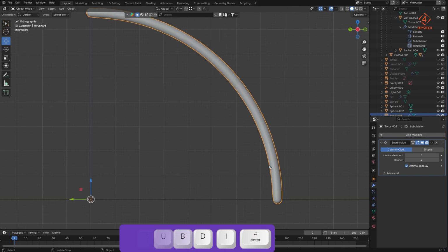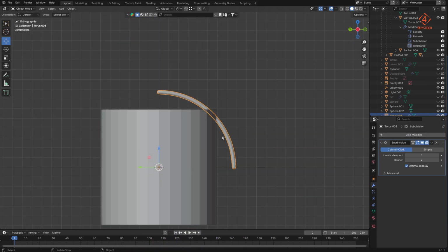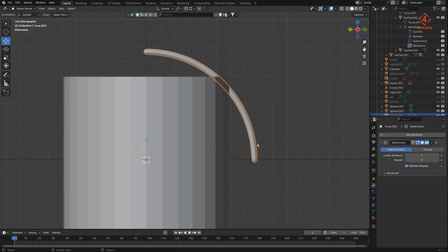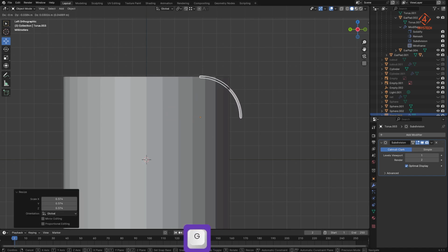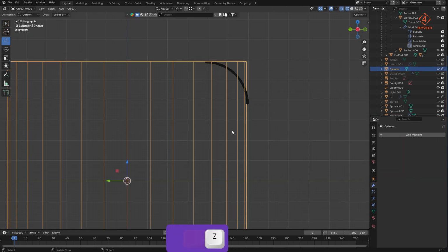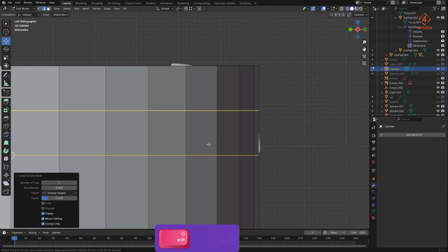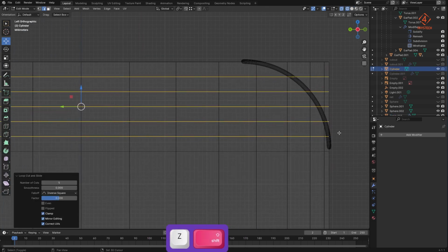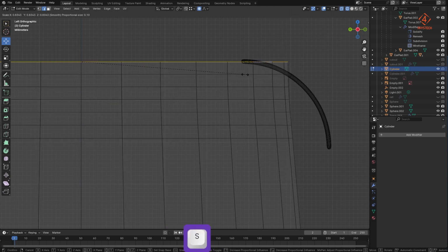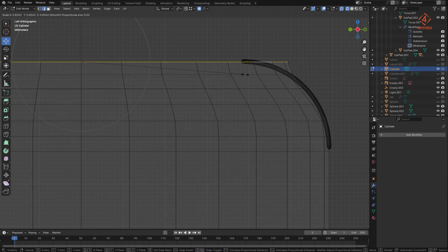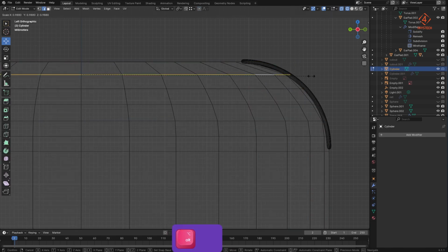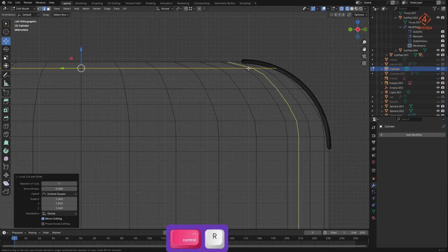Let's add a subdiv, and you see this rounded, proper part of the torus. I'll scale it down, place it on the edge of it. So let's bring in an edge loop, Control R, make a few more of these, and I'll select the edges, and using proportional editing, I've got them all settled up. I can create more edge loops as and when needed.